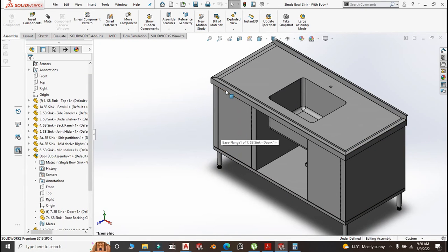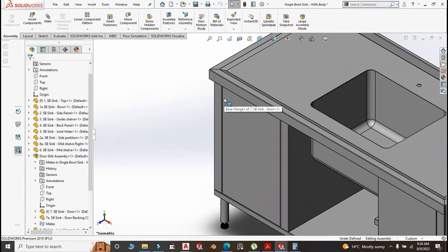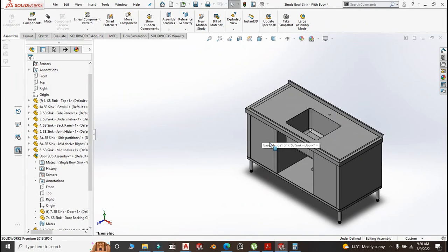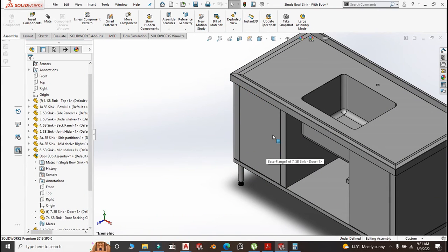Now, the part that is remaining here is to bring in the bushes for the doors. I'm pretty sure you can do that, because it's all about fabrication, and you don't need flat pattern for anything. For the bushes, you machine a bush of dia 25. You do 2 bushes here and here, here and here, because the doors are supposed to be swinging like this. Then you do handles, and the handles, please don't weld the handles when you're doing.